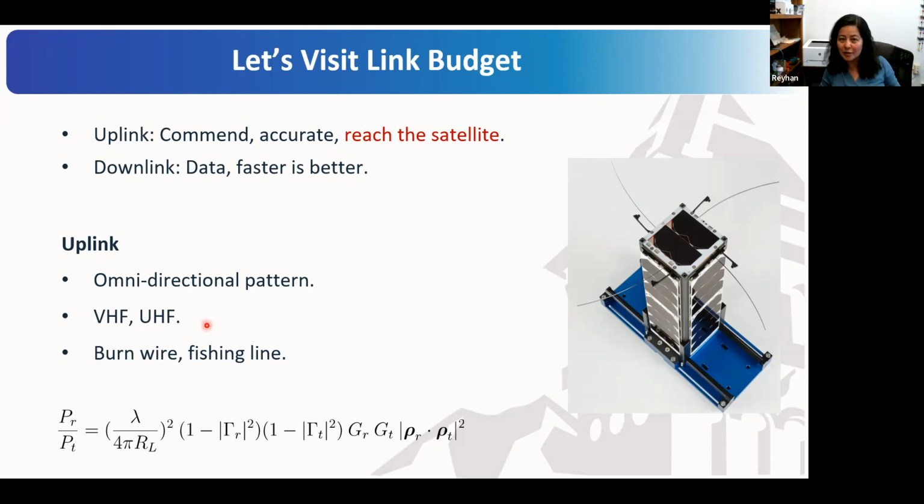The satellite will not understand us, right? So therefore, to increase the received power, when you look at here, the biggest factor here is the space loss, right here. The distance between the Earth and the satellite, we can't do anything about, but we can increase the wavelengths. So that means we will lower the frequency. That's actually why the uplink antennas are often UHF, or maybe even higher VHF. So that's why we got stuck to these deployed wire antennas.